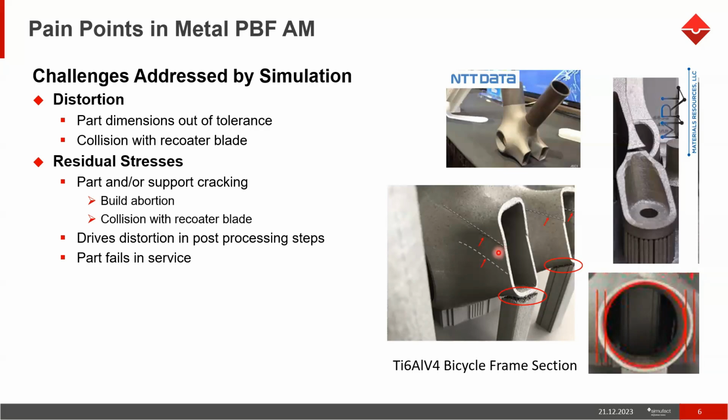So sometimes what will happen is these support structures can separate from the part due to some heat induced effects. These can separate from the part due to residual stresses that can concentrate at these regions actually. So can we simulate these kinds of effects in the simulation, and can we reduce the defects in these kinds of parts actually?